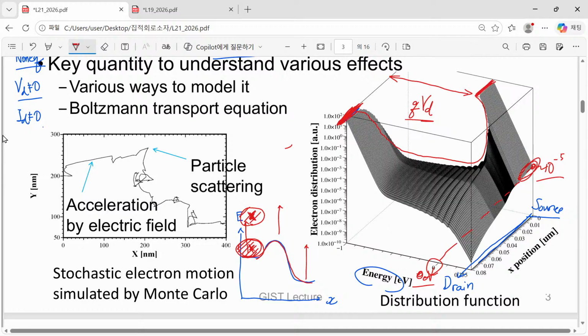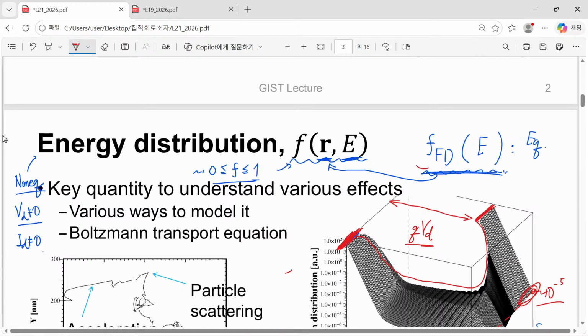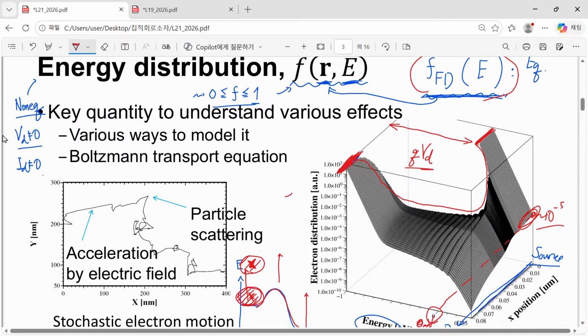After that, we have just exponential decay of occupancy. Why? Because in many cases, if it is a Fermi-Dirac distribution, equilibrium distribution can be expected to behave just like an exponential function. The tail of a Fermi-Dirac distribution function just looks like a Maxwell-Boltzmann distribution, and it is just exponentially decaying. So now you can see here, exponential.